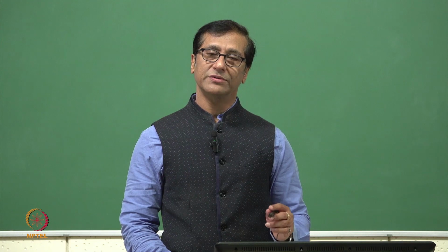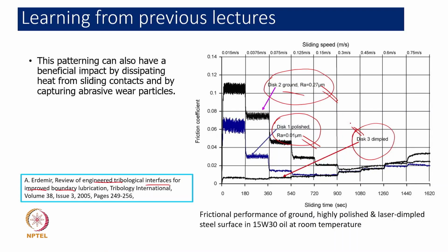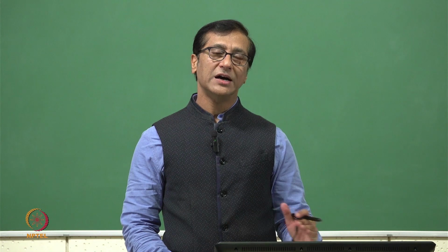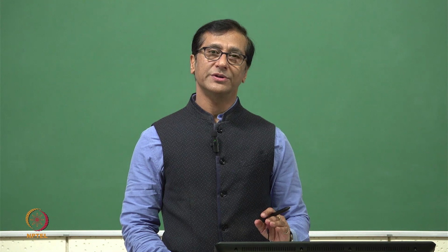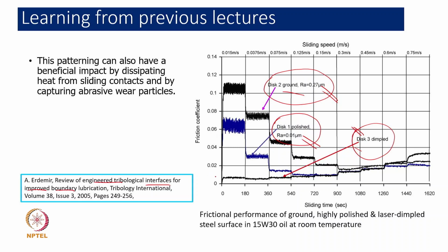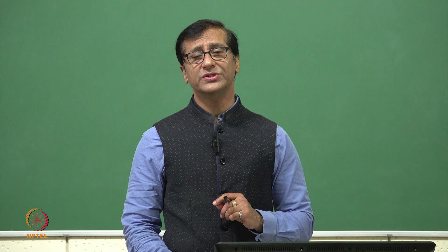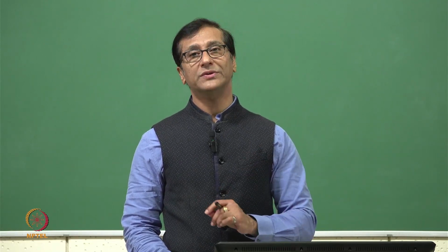However, a surface texture, even though it has some surface roughness, is a texture, and because of the texturing, randomness is coming down, and we have good pockets where debris will be accumulated. It will not cause three body abrasion, and it will not cause additional scratches. That has been compared, and it shows very clearly that the coefficient of friction in the case of the surface texture, even if it has a high roughness, gives better results compared to the polished surface and the ground surface.